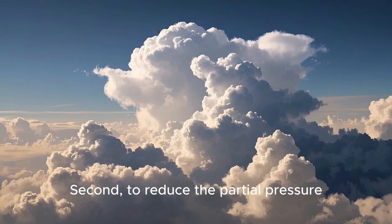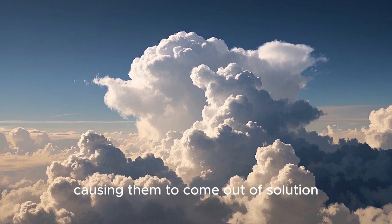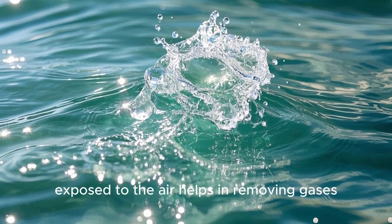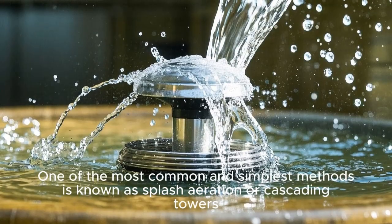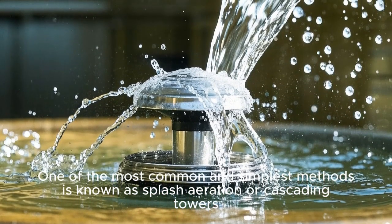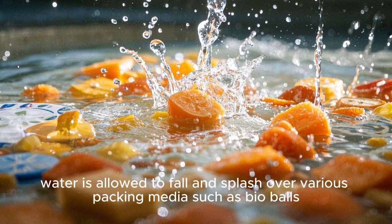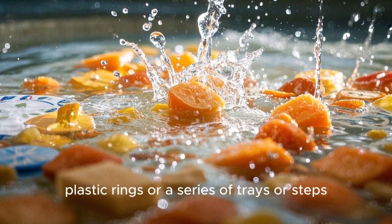Second, to reduce the partial pressure of gases in water below their saturation point, causing them to come out of solution. Let's first talk about how increasing the surface area of water exposed to the air helps in removing gases. One of the most common and simplest methods is known as splash aeration or cascading towers. In this method, water is allowed to fall and splash over various packing media such as bioballs, plastic rings, or a series of trays or steps.